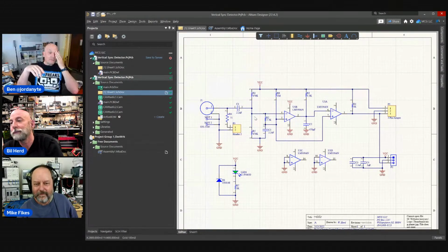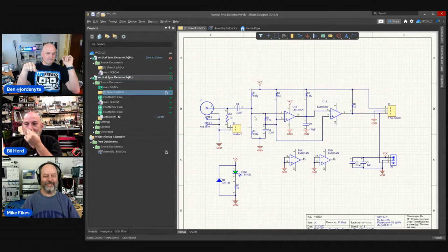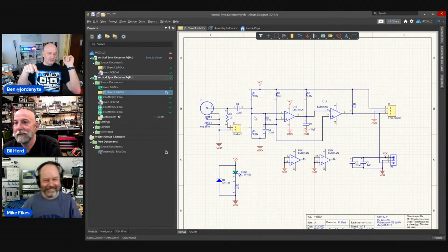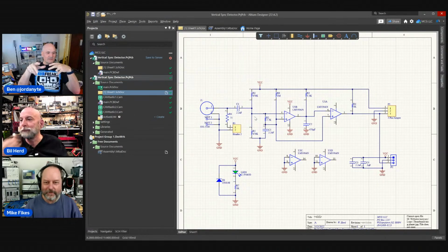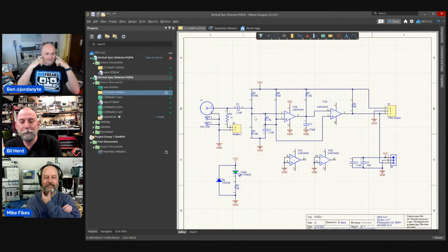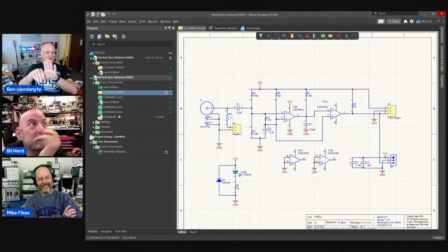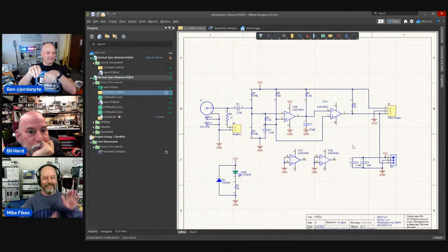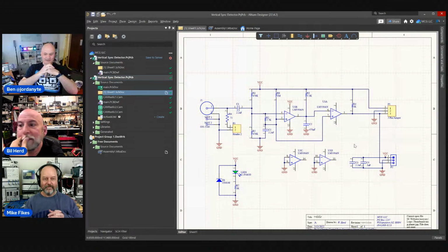If you put a stock chart into this as a waveform, that's what I was suggesting to build, a stock chart. Yeah. What you have is a moving average filter. That's your RC. That's it. Yep, the time constant is set by RC, and your comparator is giving buy and sell signals, when the stock price quickly makes a change, positive or negative, around the moving average and crosses the line.